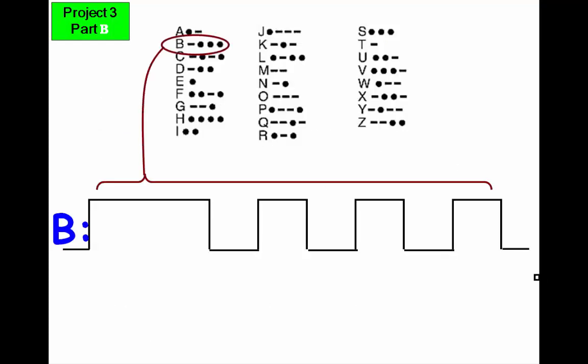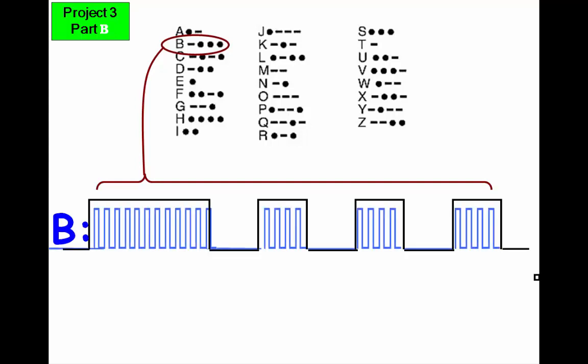So once again, let's suppose that we want to represent the letter B. As before, in the case of simply illuminating the LED, we need time intervals that represent the dash, the dead space, and the dots. But we also need a faster timing loop to produce the audio signal that will be used to energize the loudspeaker during the times that a dot or dash is present. We recommend that you produce an audio tone in the range 500 Hz to 1 kHz because it's easy to hear and not annoying to your neighbors.